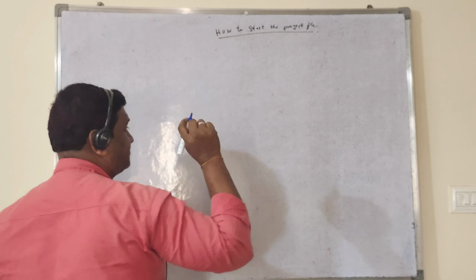After the template file appears in the drop-down menu, you have to click Project, and there is one more option, OK. After clicking Project, select OK below. After clicking OK, what will happen? A new project file is going to be created as per the selected template. Whether you take the mechanical template, it will have all the mechanical families, the setup, everything. If you take the structure template, the structure families, everything will be there. So this is the way we create a new project file.